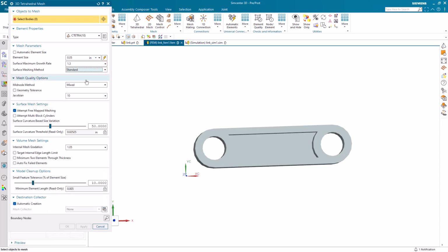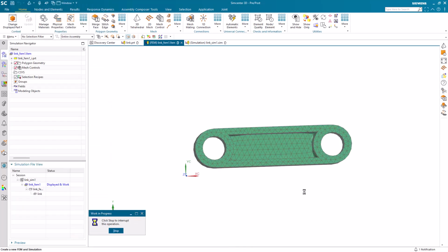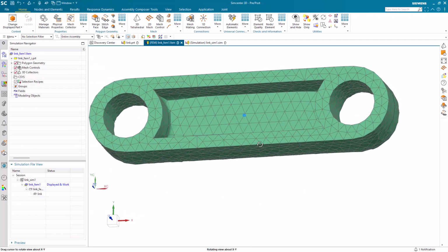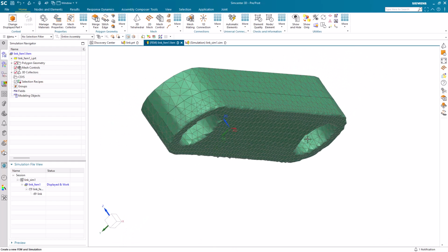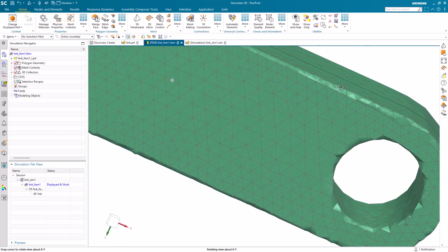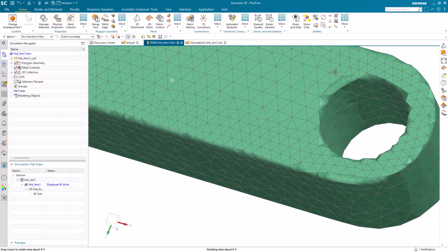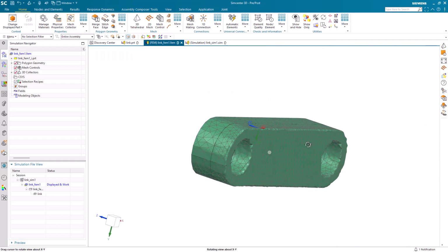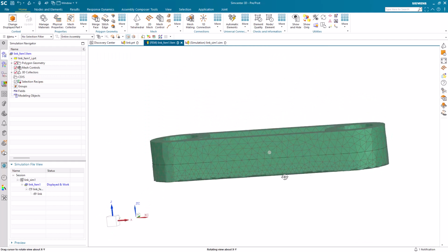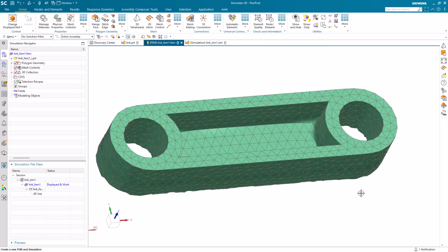Now if we had selected the standard meshing method, which should be the default, what you'll find is a mesh that may not be satisfactory. So you can see, because we don't have any hard edges except for 2 in the part, we may get some poorly shaped elements, especially around the areas where we would expect to have a hard edge, but we don't have one because it's an STL file.